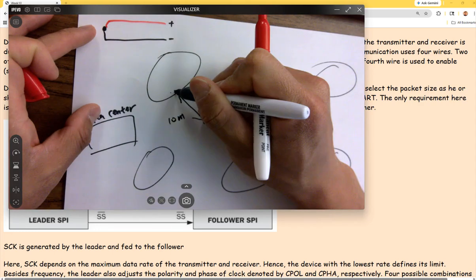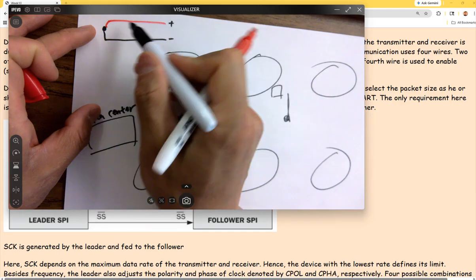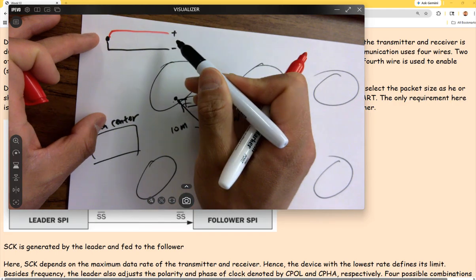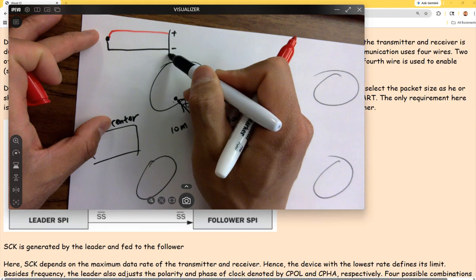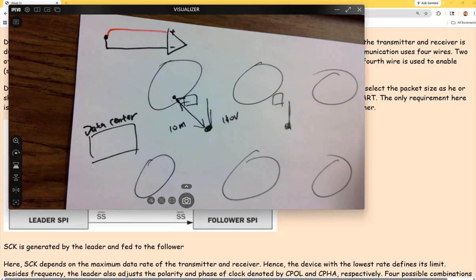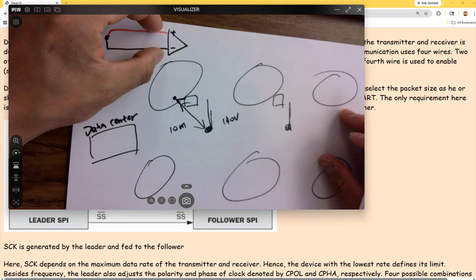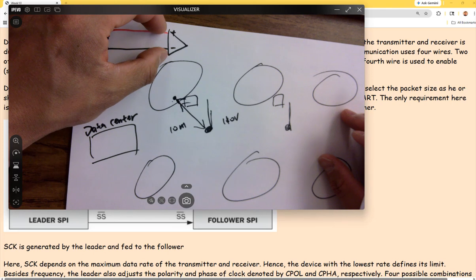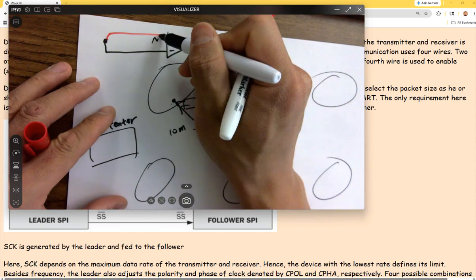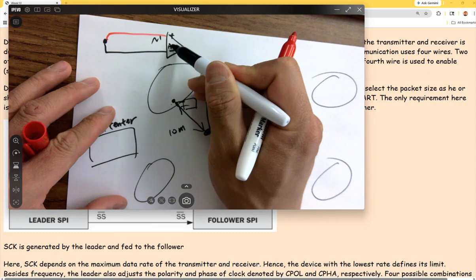The thing is, you have to drill a hole to the hot top here, right? And then have a thermocouple here. And what's next? Thermocouple, microcontroller. No, actually, an analog to digital converter, ADC. You have to amplify it first, because you're not expecting large voltage changes across the thermocouples. Otherwise, it becomes a power generator, right? It's only millivolts level, and all these analog changes have to be amplified, right?